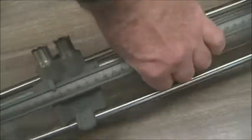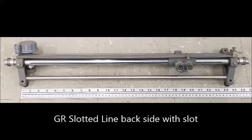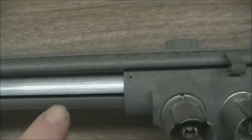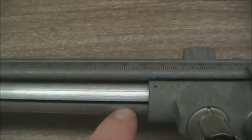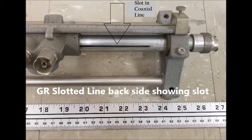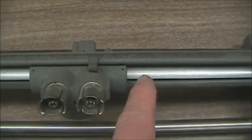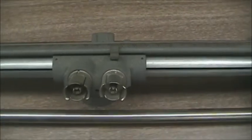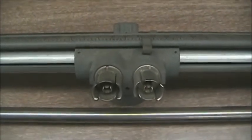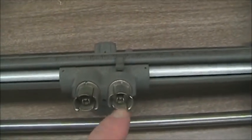Now, the reason why we call it a slotted line is if I tip it over, you can actually see the slot cut into the coax. That little slot goes the full length of this line, or near the full length. And then there's a probe that is connected to one of these connectors, and that goes down in to measure the RF signal. There's a lot more about that in the handout. You can read about that. The second port here was for tuning for the probe.